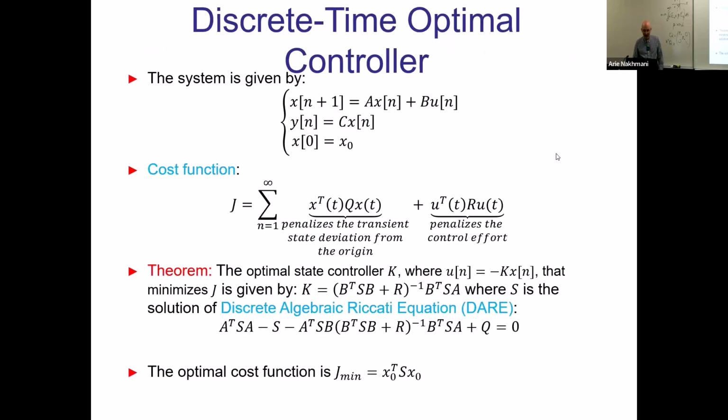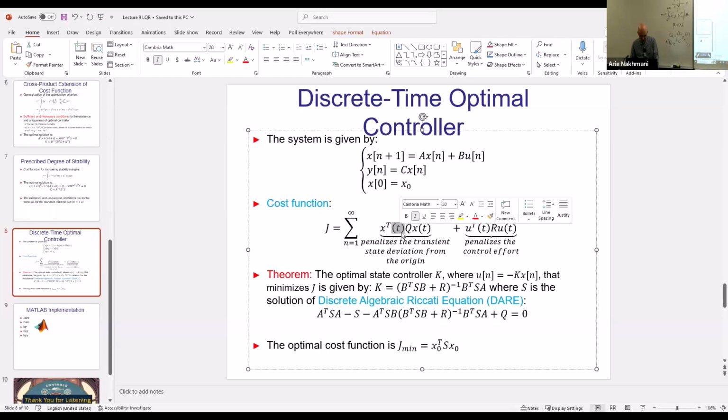And the last thing in the theory, before we get to actual theorems and proofs, as we love in that course, is the discrete time optimal controller, which you can implement in computers for discretized systems. So here's how it works. This is your discrete time system, as usual. Your optimization criterion, instead of an integral, has an infinite sum, for obvious reasons, because all of the states are discrete. And again, the mistake here is that this should also be a function of n, of course. So all of them are supposed to be n here.